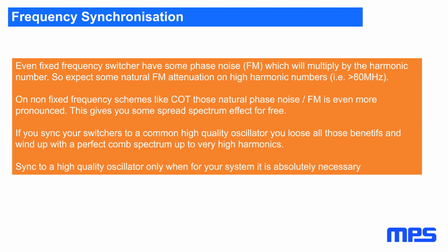band. If you have an internal oscillator, it is not crystal stable; it has some phase noise, some FM. The FM goes up with the harmonics, which means that something which looks pretty nice at 1 megahertz will have a decent phase noise at 100 megahertz and above. So a normal switching regulator gives you some natural spread spectrum, some natural phase noise.